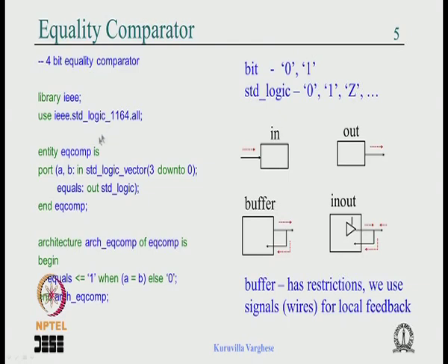So that is the code in a nutshell. You have a comment, you have a library, you have a use package kind of construct, you have an entity with port, mainly within the entity is a port, direction, the data type, the multi-bit declaration, then the architecture. Before the begin there is a declaration. In the statement region you write various statements, then the description is over, okay. So that is in a nutshell the basic VHDL code. You can use various keywords, various names, and let us move on to the slide.